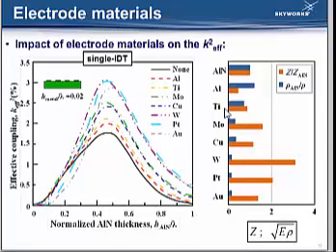Similarly, this figure shows the effect of electrode material on the coupling coefficient for the single IDT configuration. Again, when the aluminum nitride is sufficiently thick, in the orange circle, the coupling coefficient is enhanced and proportional to the acoustic impedance of the electrode material, because larger acoustic impedance gives larger reflection coefficient. And when the aluminum nitride is very thin, the heavier metal has stronger loading effect.